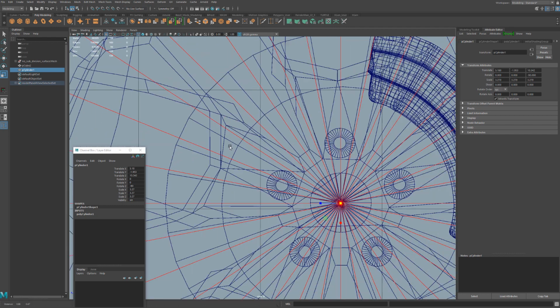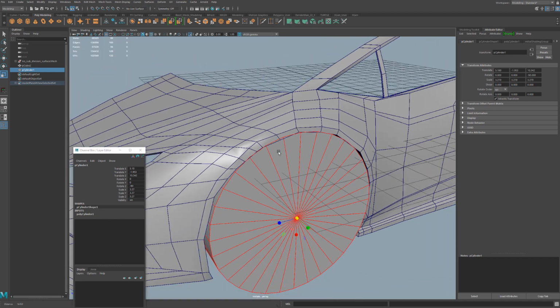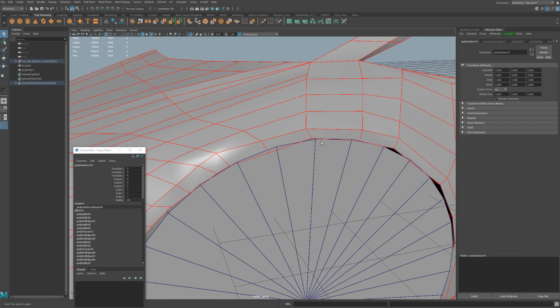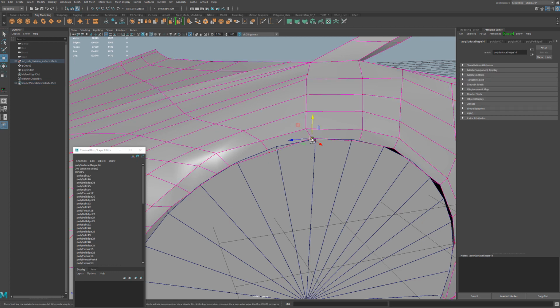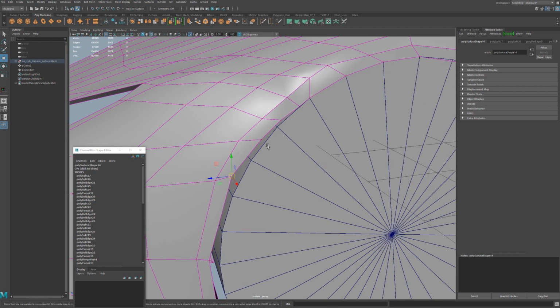And this is snap where the middle of that wheel is, so this should be in pretty much give or take the right position. So now what I can do is start taking these verts. Anytime that you're pushing off the silhouette, make sure that you have vert snap disabled. And now you see that cylinder is making our life a lot easier.